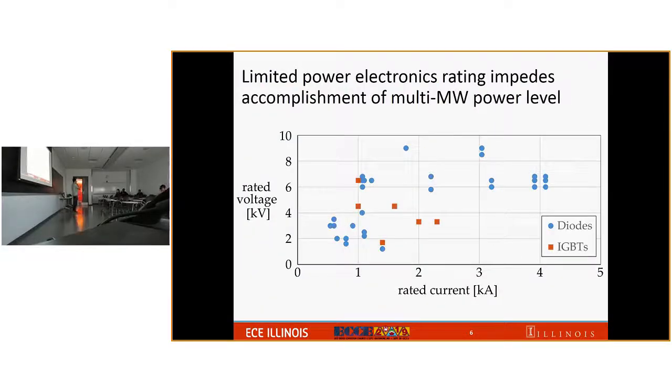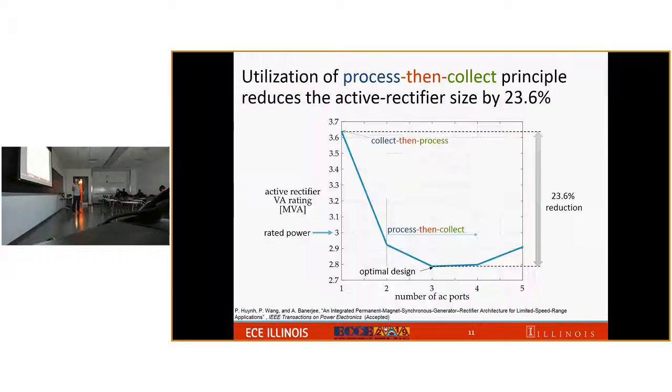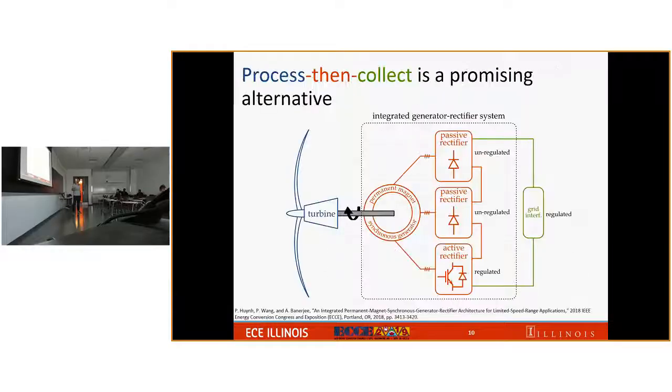Yes. So in this slide, they're just 3. So I'm guessing the active rectifier will be built with IGBTs, correct? Yes. So which means you're looking for kilovolts at the end. You'd have to distribute the voltage across the passive and the active in such a way that each passive rectifier is able to handle more voltage than the active rectifier. Is that correct?